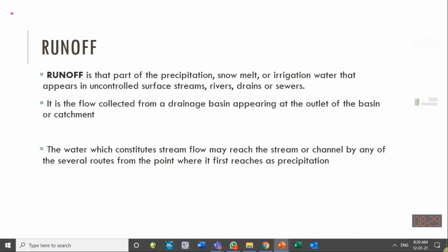But in case of snow melt or glacier melt, temperature plays an important role. So in rainfall runoff models, temperature is not much important if I have the evaporation values available. While in case of snow melt and ice melt models, we have some models which are capable of doing this kind of conversion. So we need temperature data at that place. If temperature rises above the melting point, then we say, okay, now this is converted to water. Now runoff or infiltration or other phenomena should be calculated.